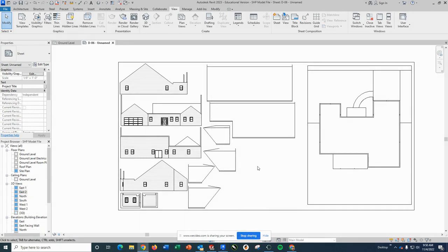After you get all your views on, so all of your roof panels, all of your walls that might be hidden in little niches or by other walls, all your 4 elevations, your plot plan, all organized. This is what your sheet should look like. You'll also notice I did leave myself some open space here, because after I cut all this out, if I was to have a problem with a wall, lose one, break one, that sort of stuff, I'm going to have a good section of material here that I can cut out of my own scrap again if I needed to. So that's a really good place to be in.